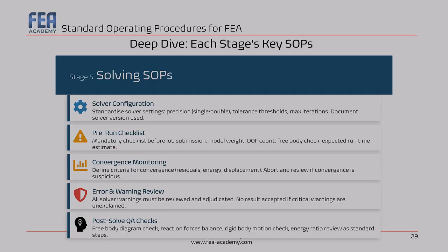Also, you have to define your convergence criteria before you run, not after. For a nonlinear analysis, specify the force residual norm, the displacement norm, and the energy criteria. For a linear analysis, check that the reaction forces balance the applied force, the applied load, sorry. Check also the residual error. It should be very, very small.